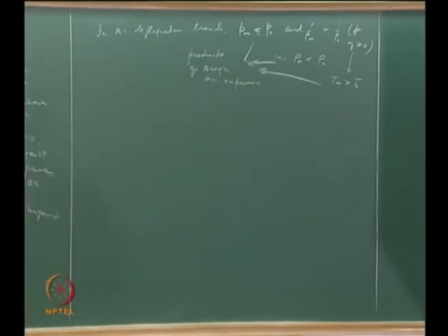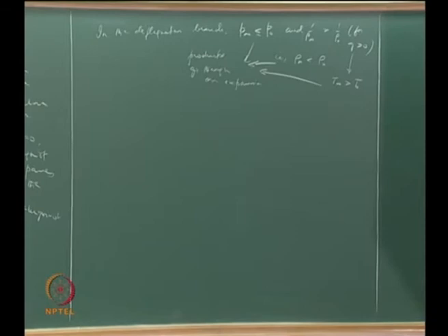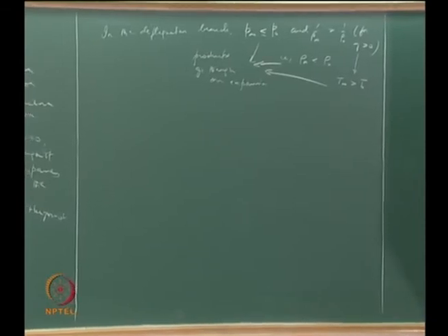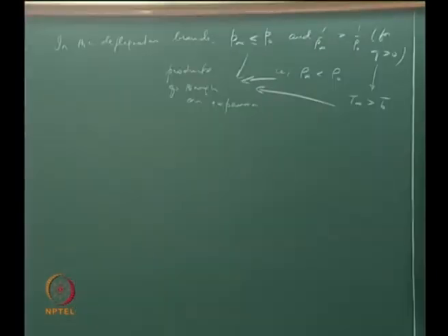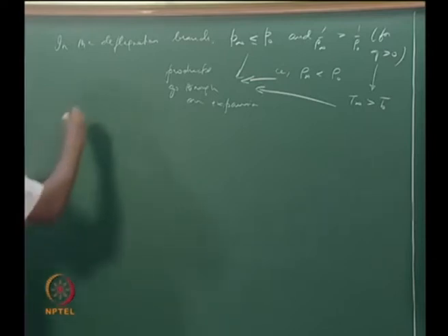It's when you have an expansion that your pressure decreases and your density decreases even with the temperature increase. So a deflagration branch corresponds to an expansion wave.